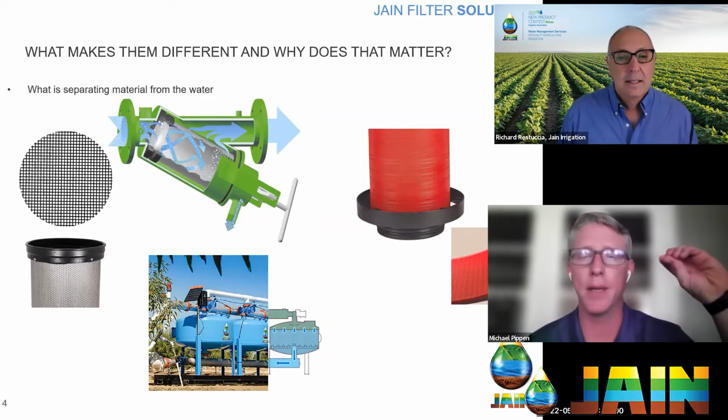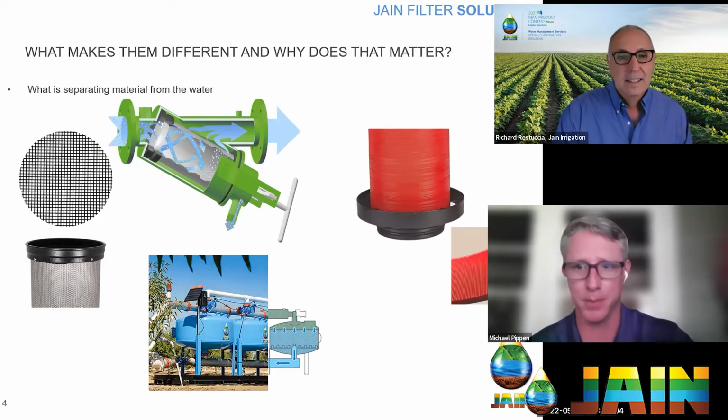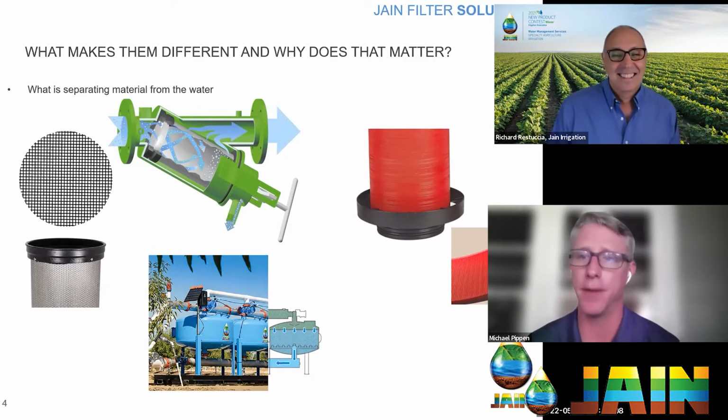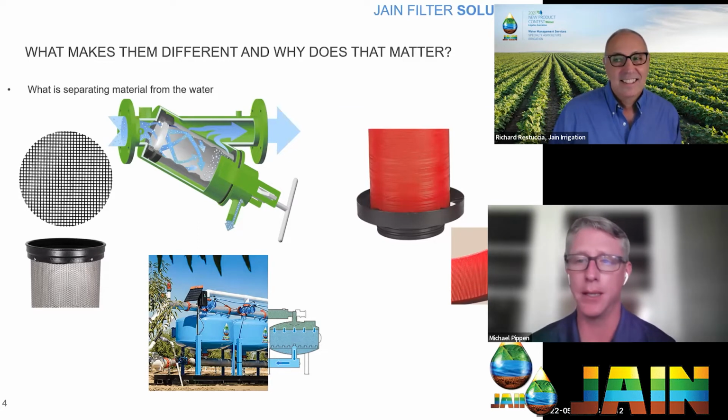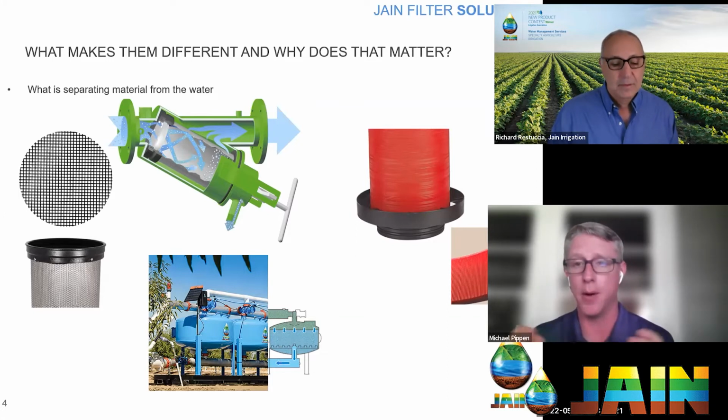One thing that I think is worth mentioning is this is a very specific sand. We didn't just go in my backyard and dig up some sand and put it in there. That would be a bad idea. That would not work. This is a very specific type of sand. Most commonly we use a carbon silica sand. It's been graded, it's been sorted. It is all very similar in size, which is important.